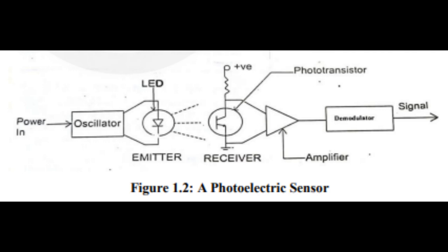1.4.4 Fluid flow switch. A discrete event sensor commonly used in process control is the fluid flow switch. This device is analogous to a limit switch in mechanical systems. It is usually employed as a device to detect when a fluid traveling in a pipe is over a specified volumetric flow rate. Such a sensor can be used to govern the speed of an upstream pump, reducing it when the flow is too fast.